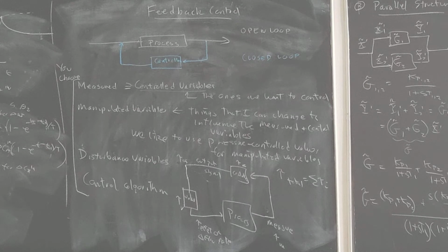Well, what does that mean? Simple example, you're in the shower. You get into the shower. You say, I have to get to school to hear my control class. So you jump in the shower, and the water's too cold. So you turn the hot water valve, and it's still too cold. What do you do? You turn it some more. But if there was a long delay, then you've turned it too much.